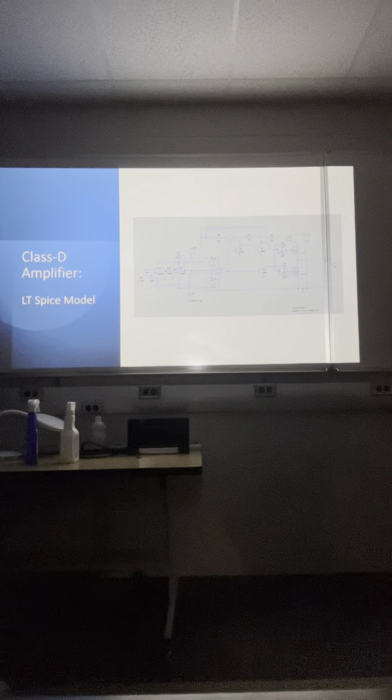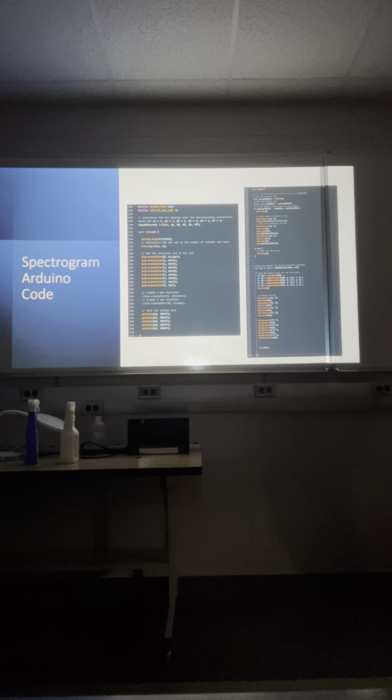All right, there are sources, that's the end, but let me go back. One other thing I wanted to mention is a couple of things we tried. One thing we tried incorporating a couple of nights ago was Bluetooth, where we could send a Bluetooth signal, like Bluetooth audio, as the input. That did not work because the Bluetooth module we were dealing with couldn't transfer enough data fast enough. So that was a dead end, but it was something definitely cool we wanted to try.